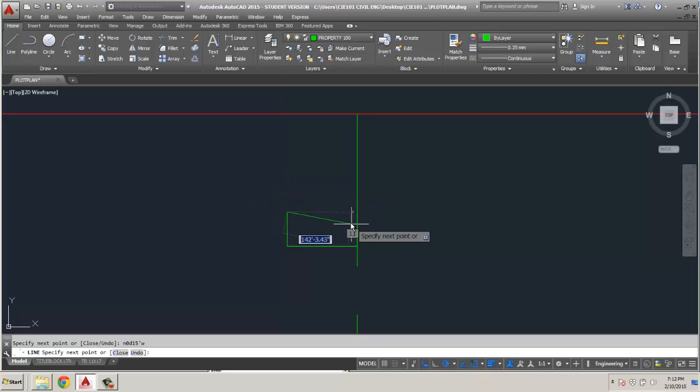There we go. Now we're going to come back and key in a distance of 151 feet, 2.4 tab. And it's north 89 degrees, 55 minutes east. Brings us back to the point of beginning. So that ties it all together.